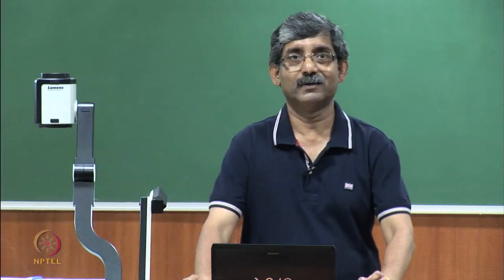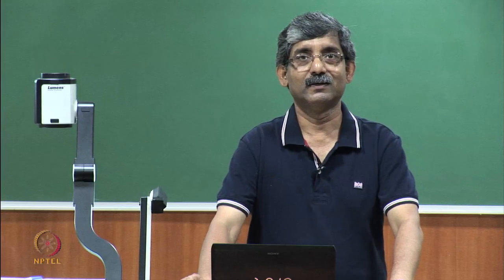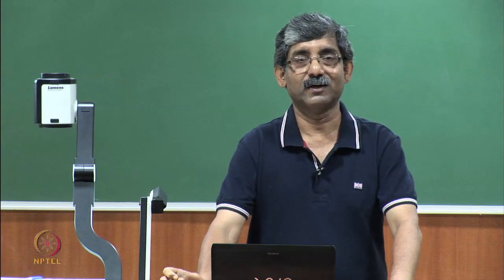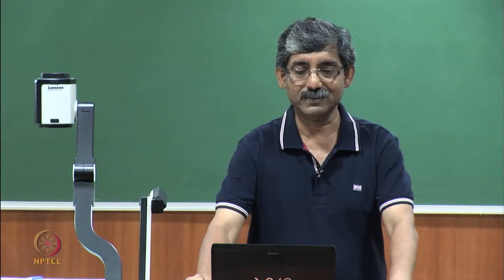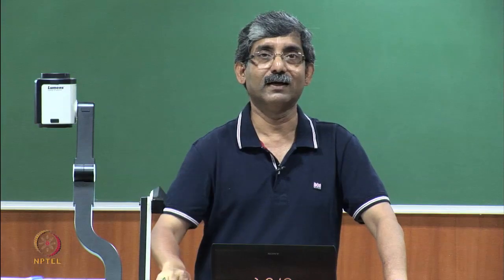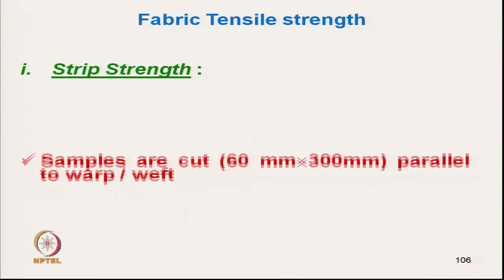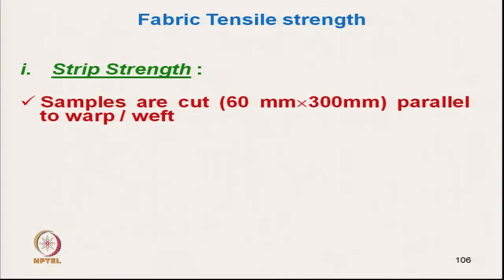Hello everyone. Now we will start the tensile testing of fabric. So, the strip test, which is very common for fabric tensile testing. So, here the samples are cut in 60 millimeter by 300 millimeter parallel to warp or weft.